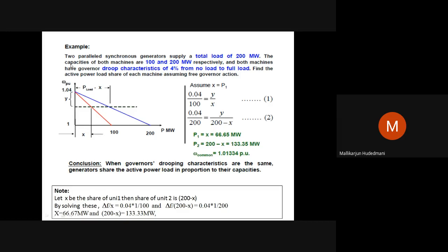Like that, along the y-axis, from the reference point of 1 unit speed required, you just scale up and mark a point at 1.04. This is to say no load. When the load on the machine is 0, along the x-axis the power scale is 0, and only vertically you will be scaling up to 1.04. From this point, along the power axis, 0, 10, 50, 100, 200, like that, power points you can mark incrementally. Let us say 0, 100, 200. Equally they are marked 0, 100, 200.